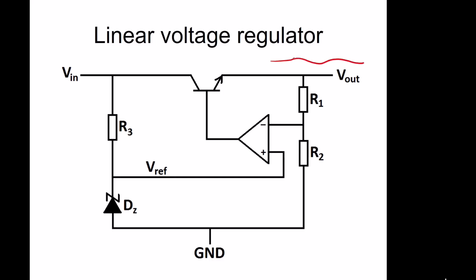As it goes up, the transistor will switch off, so it'll start going down, and then when it goes down too low, the op amp, the comparator, will go high, switch the transistor back on, and then the voltage will start going back up again. So this is quite a small ripple. This will be less than millivolts ripple, so it's very small because the gain of the comparator is so high, and because this voltage reference point here is stable. So it doesn't matter what this input voltage is doing. This can fluctuate quite widely, high and low.